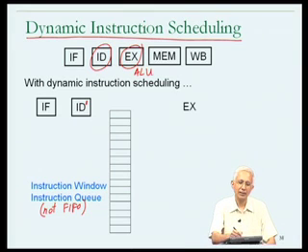Specifically, there was an ALU, which was doing the execution of the instruction, and it was used for add instructions, it was used for subtract logical instructions, but it was also used for load word instructions to calculate the effective address, and further it was also used for branch instructions to calculate the branch target.